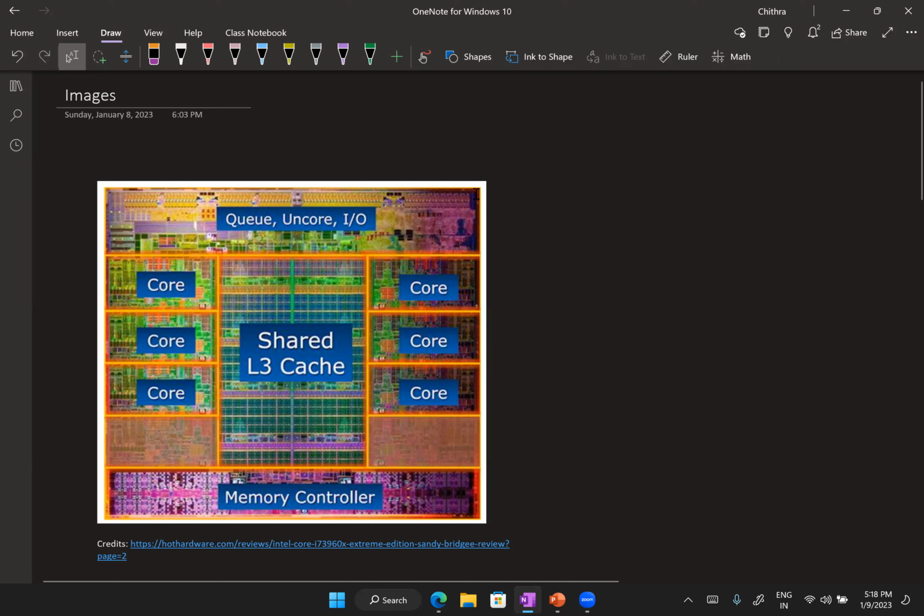So now, when you are running an operation on your laptop, such as playing a movie, we know that all of these logic gates involved in these cores as well as the memory are going to switch, correct? And we want to be able to sequence these events correctly for that operation to be run correctly. Now, for this, we synchronize all these operations to a clock edge. So the first major application of a clock signal is synchronization.